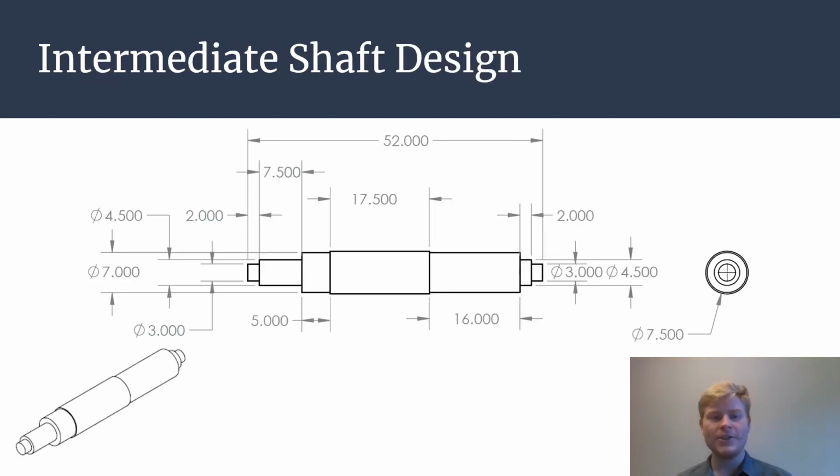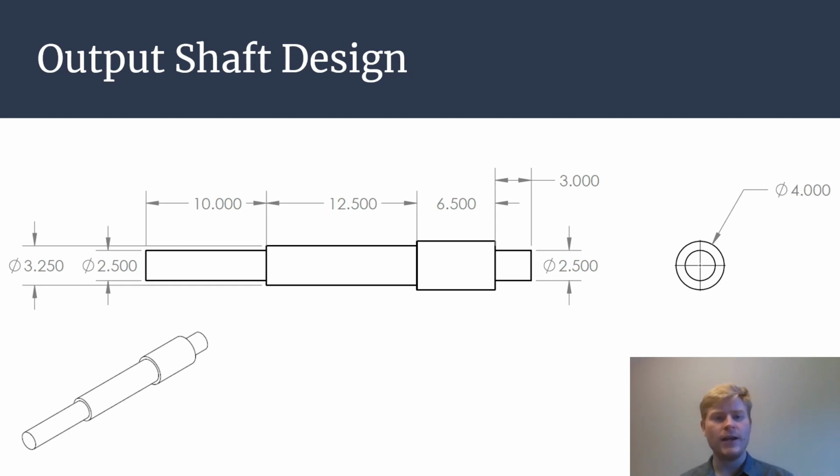The intermediate shaft is shown to have a 52-inch length and possesses a step design similar to the input and output shafts. The step design allows for the bearings and gears to be easily and accurately located onto the shafts. All shafts possess steps that ensure the gears are mounted in line with one another to ensure full meshing and no undesirable offsets. As can be seen with the output shaft mechanical drawing, all shafts were designed to reduce mass where necessary while abiding by required safety factors.